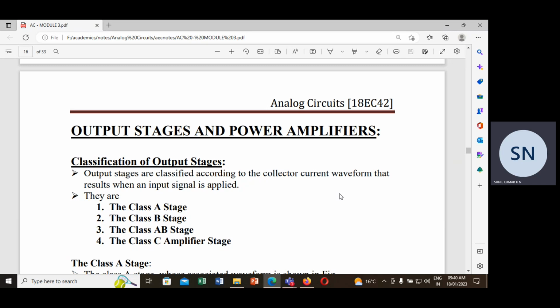Here it is non-inverting, because if you don't connect anything here and give any signal over here, the same type of signal will appear across here. The output and input are in phase, hence it is non-inverting. Whereas when you apply the input over here, the other input is made equal to 0.